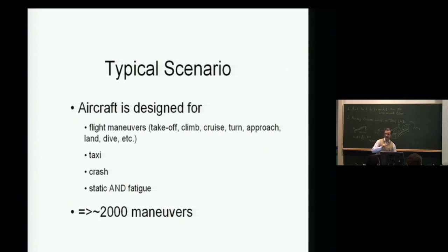So let's take a real scenario here. This is real life now. To design a whole aircraft, you have to take it through all the possible maneuvers. It has to make turns at different radii, at different rates, accelerations. It has to do climbs and dives. It has to even crash and so on. You have taxi, crash, then the flight maneuvers, and then all these are static and fatigue versions, which ends up being a list of about 2,000. It's at least 1,000 if you do it right, about 2,000 maneuvers. So that means 2,000 load cases.